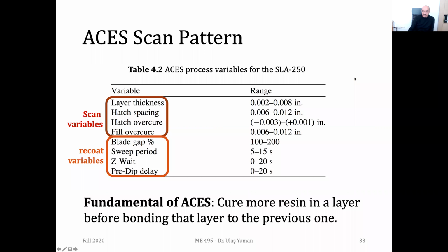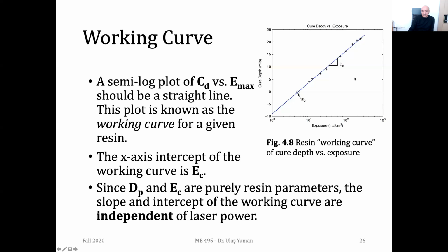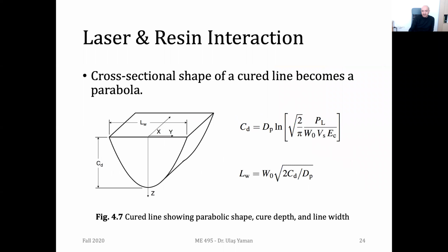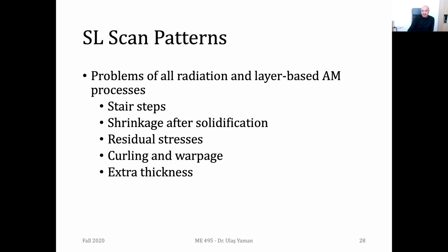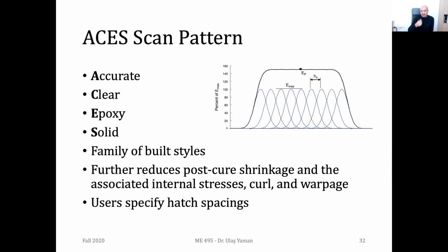And if you remember, let me come to the equations. The curing depth, or here less. If your current exposure value is higher, your critical exposure value will be relatively low, and so this will result in a higher curing depth. And you can even cure more difficult materials. But the biggest disadvantage is that you will spend more time for doing the same fabrication.